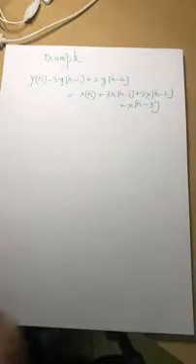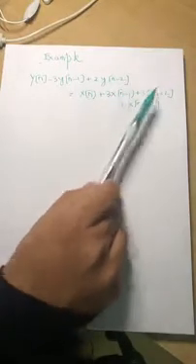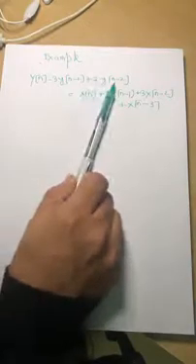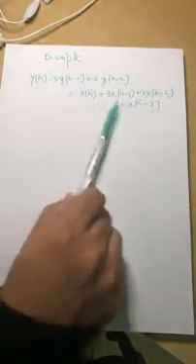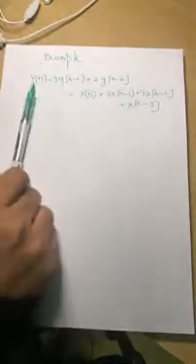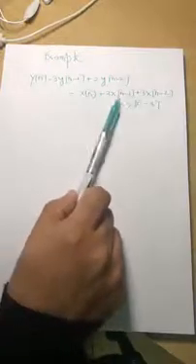Usually in signal processing, especially if you go work at any place, you will only be dealing with a difference equation, and it is very simple to implement. How? You get an input. You have the previous input, previous to previous input, previous to previous to previous input. You have the previous output and previous to previous output. You would just multiply these, add them together, and bring this to the other side, so you get y of n. Once you get the next input sample, your x of n becomes x of n minus 1.